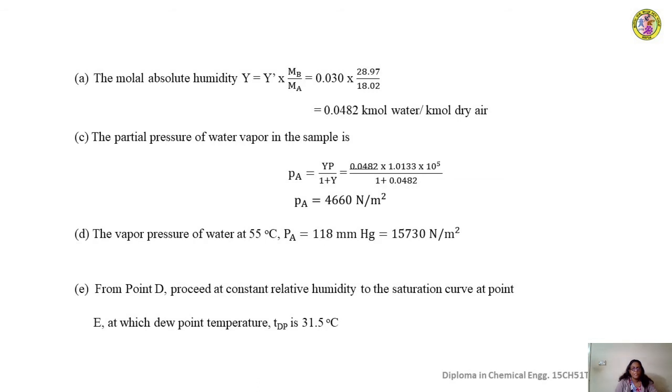So which will meet the humidity chart at point E. So after you construct the line DE on a humidity chart, from that point, okay, sorry, this is a step where you are estimating the dew point, so not the wet bulb temperature. From the point where the dry bulb temperature line and the humidity line are meeting, you have to draw a straight horizontal line.